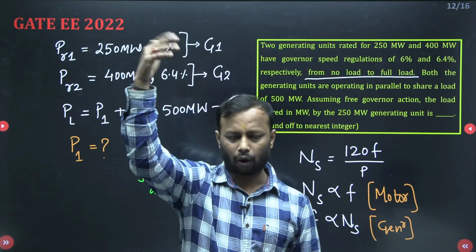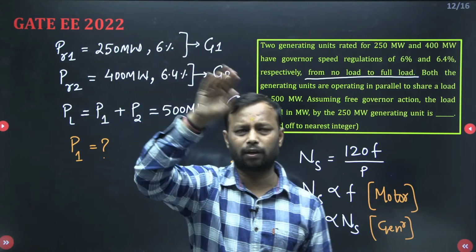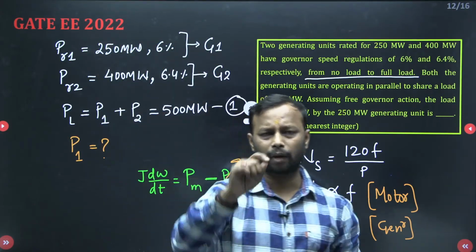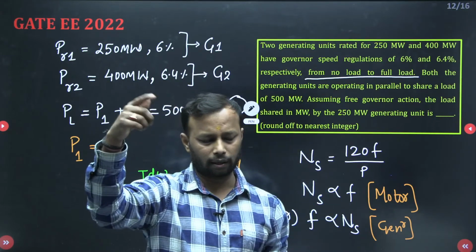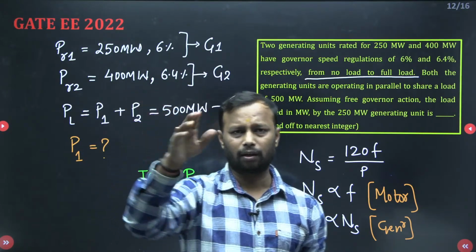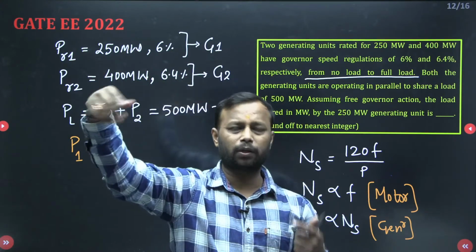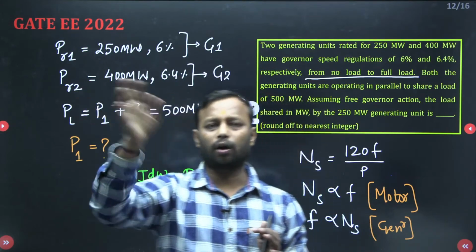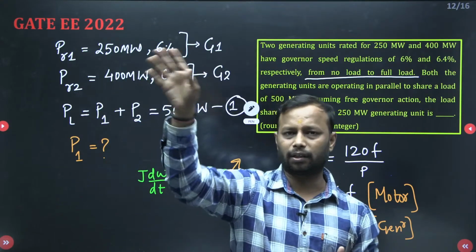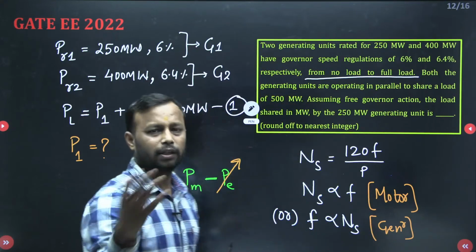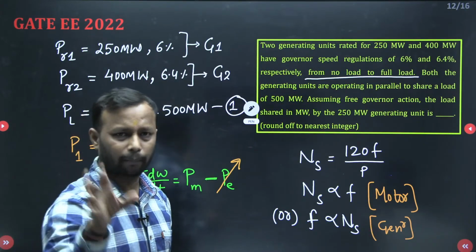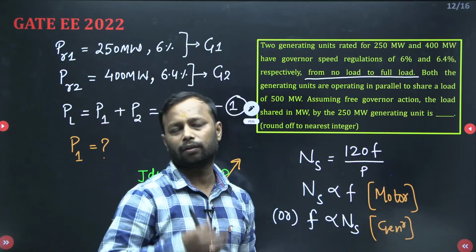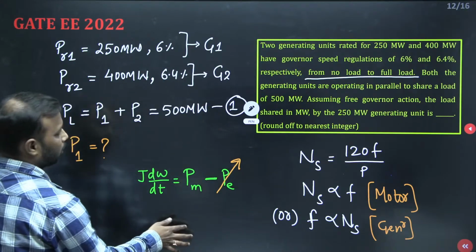This occurred in 2014 or 2012, somewhere like that, in Delhi or in Northeast Assam. I'm not able to recall the Northeast state name, but power from Delhi had to be transferred to the Northeast side. Because of the load, it was not getting transferred, and the whole state electricity was shut down. That is nothing but the grid failure, and it happens because your frequency is reduced to a drastic level. Okay. Come to this question.